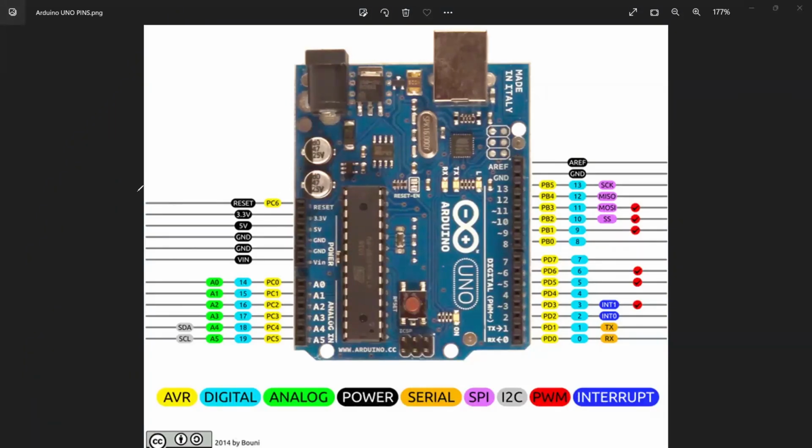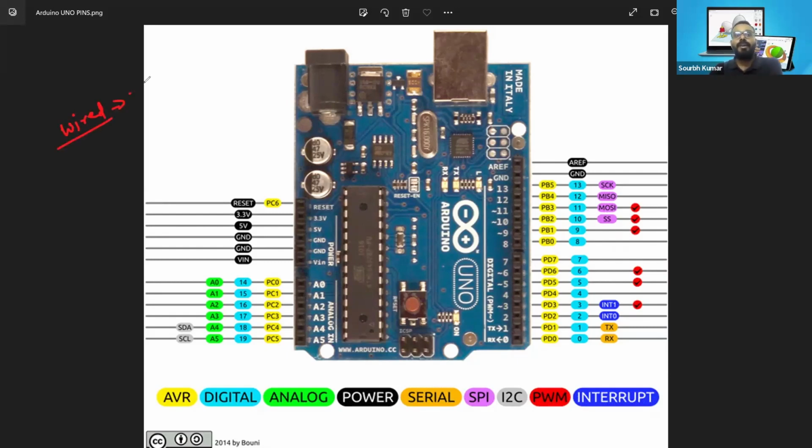And one more thing, what do you think is better: a wired one, a wireless one, or an autonomous one, if you want to cross this obstacle? See, the wired one will give you difficulties because one person will be engaged all the time to control the bot and handle the wires. It will make it difficult to complete the arena, so I won't recommend the wired one. So go for the wireless one, and if you can build the model out of an NRF module, an NRF controller module or something like that, using a joystick and a setup to implement the same, then it will be a perfect addition to this competition.